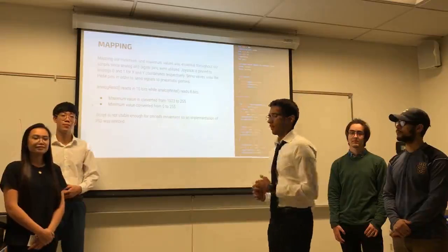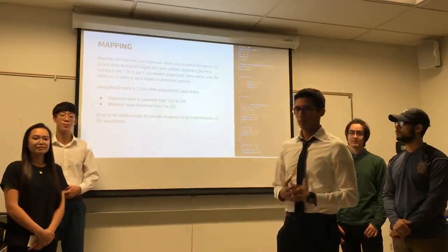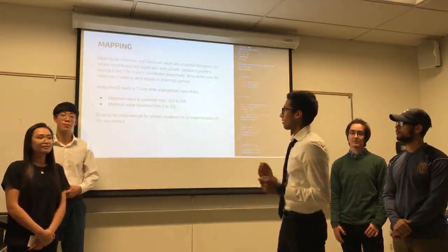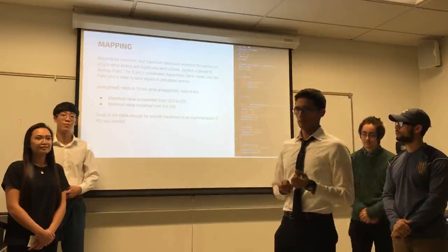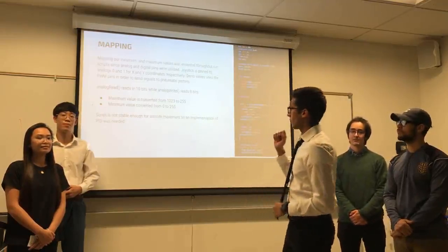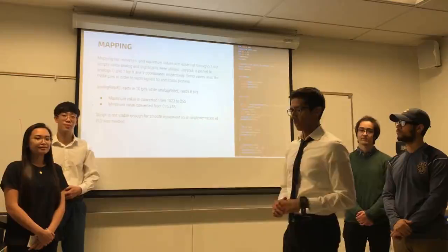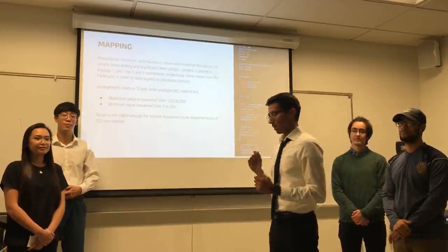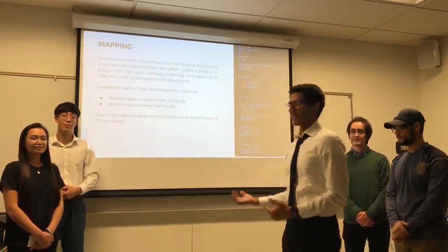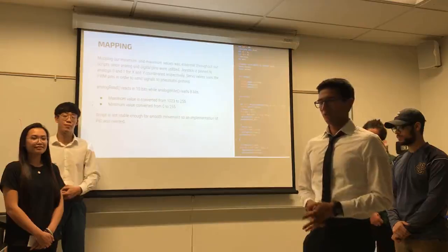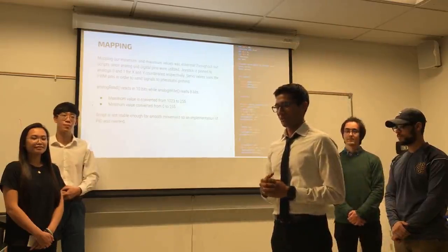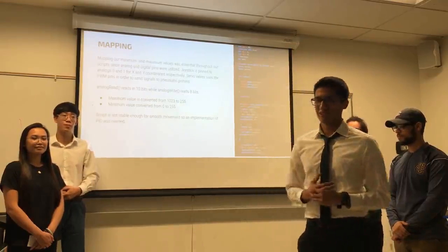So in order to obtain values from the joystick, we had the terminals connected to pin 0 and 1 in order to get those 10-bit binary numbers, and then we also used analog write to send a signal to the servo valves in order to actuate our pistons. We also use nested if statements in order for the corresponding value to send an action towards our pneumatic cylinders.